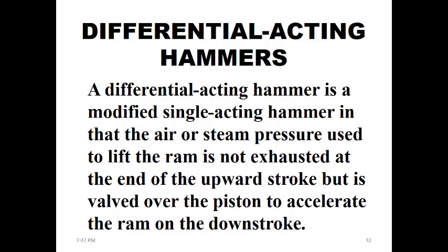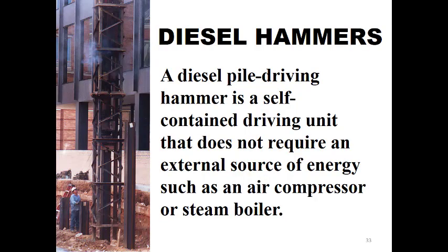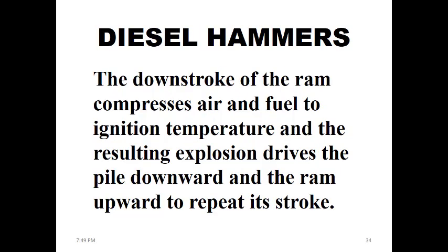Differential acting hammers are pretty similar, so I don't want to talk about them for too long, and their operation is pretty similar to these hammers. For diesel, it's actually utilizing the energy from the fuel and the explosion process, which generates the energy in order to drive the pile down the media. We will talk in more detail about this one to see how it's working, and the idea is again to have this process of moving the ram up and down and driving the pile down the media.